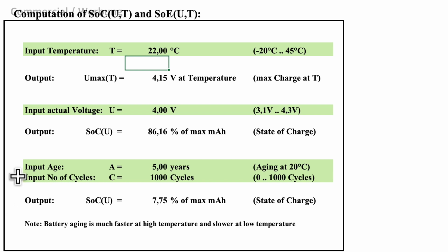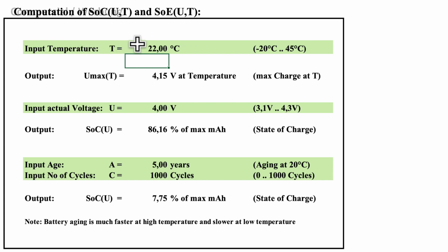Now let us quickly calculate which battery degradation the tool predicts with our parameters given from the system report. Let's assume that the battery temperature is 32 degrees Celsius when the laptop is in operation. This gives us immediately the voltage of a lithium-ion cell when it is fully charged. The resulting 4.19 volts we insert as the actual voltage for the following computation, which gives us 100% charge as expected.